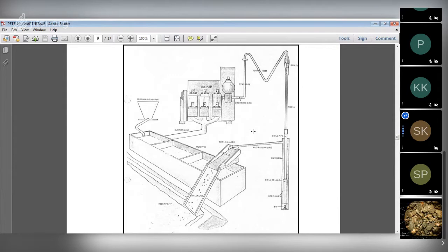So basically when we are drilling, the volume of mud is being displaced into the well, right? So it is always getting emptied. At one point in time, we have to refill it. So there are reserve pits from where we transfer mud, and we keep on preparing the mud so that the entire section is filled with mud, right? So this is how the mud system is.